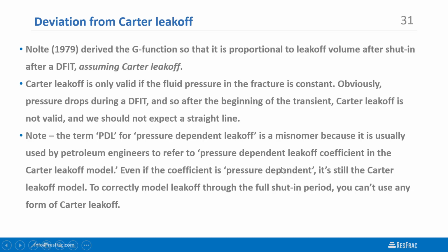Now, another clarification. I've given this as a presentation in the past, and someone said, oh, everybody knows about that. That's why we do PDL, pressure-dependent leak-off. Well, in fact, that is not what is actually done in frac simulators as PDL. There's a term called pressure-dependent leak-off. Of course, leak-off is pressure-dependent, but when people use this term in petroleum engineering, what they actually mean is a pressure-dependent leak-off coefficient in the Carter leak-off model. So people have taken the Carter leak-off model and then made the coefficient out in front dependent on fluid pressure. That is not the same thing.